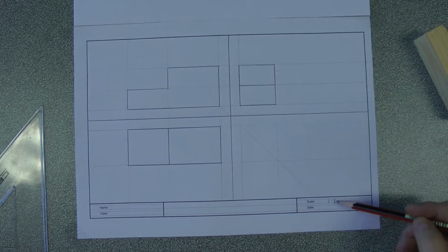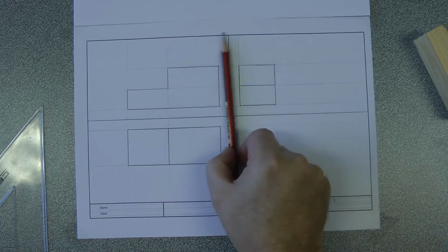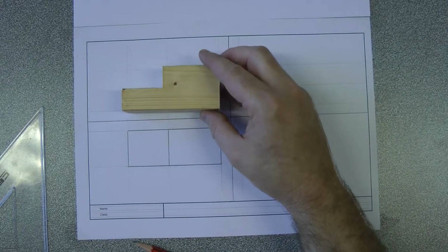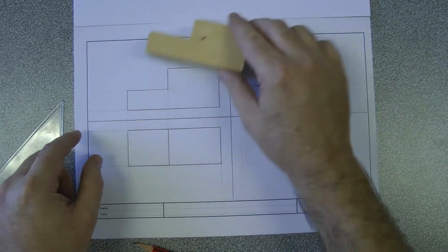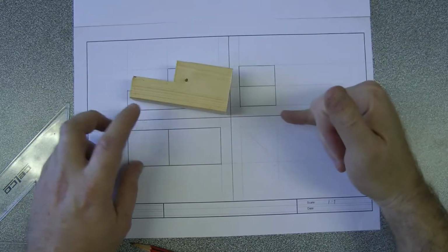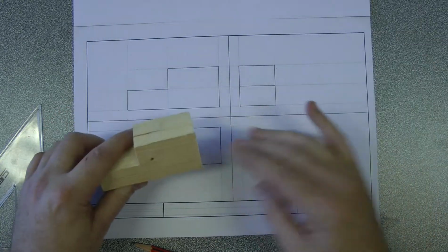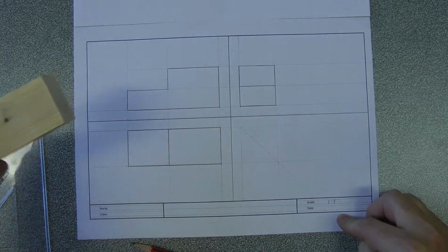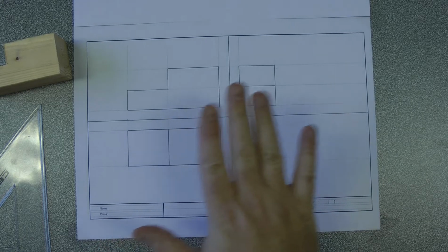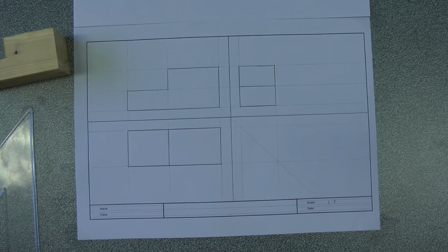It is done on a scale of 1 to 1, and these separation lines, these quadrant lines if you wish, are centered because the shape will fit in even with it centered. If the shape had been longer this way, we would have had to move this line to the right. If it had been taller this way, we would have had to move this line down. There was a limit on what we could do on either of these movements before we needed to go and increase the scale and change the scale. And that hopefully explains what you need to do to set up your drawing paper, to determine your scale, and to do an orthogonal drawing of a shape.